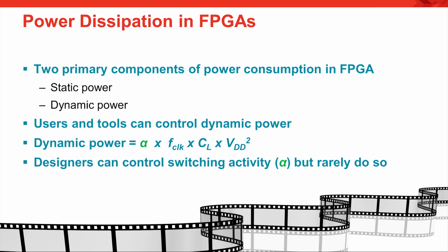Power dissipation can be categorized as static or dynamic. In the simplest terms, you can think of an FPGA as a network of billions of transistors modeled as tiny capacitors. These capacitors consume static power due to small amounts of leakage current when powered on, and they consume dynamic power when they are charged and discharged during normal operation. Besides the device utilization, static power is mainly determined by semiconductor process parameters and the voltage of the power supply.